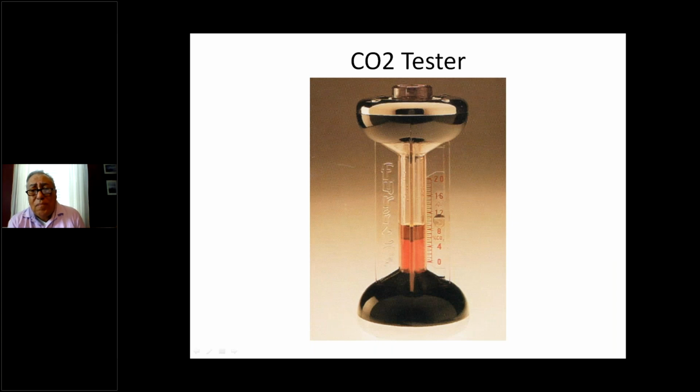And what would happen is the liquid would raise. You'd start off at 0, you'd zero it out, and it would expand inside the tube, and then you would read across the top of the column of fluid, and that would give you your reading of what the percentage of CO2 was. In this case, you're looking at 9% CO2, so you'd read it right at the top.